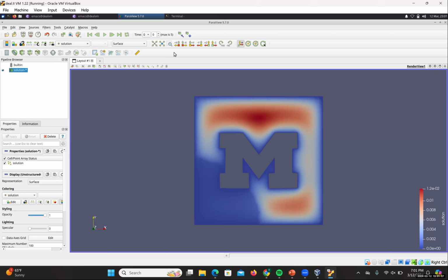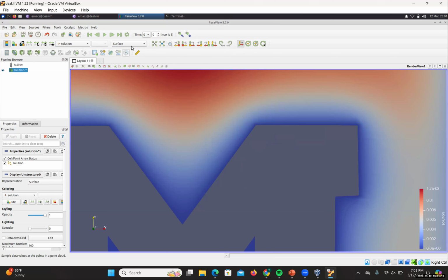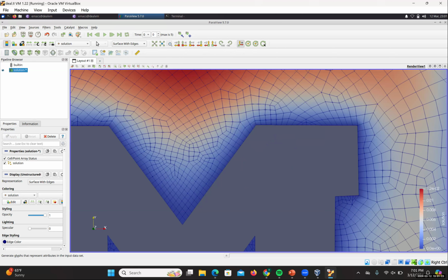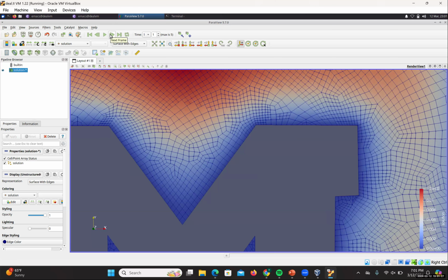And I'll just go over time another minute just to show you guys what I was trying to do here. I was playing around with those adaptive mesh capabilities that I mentioned in deal.II, and there is an option to do grid refinement in a way that tries to optimize both your gains and accuracy and how fast your next iteration of this refinement will run.